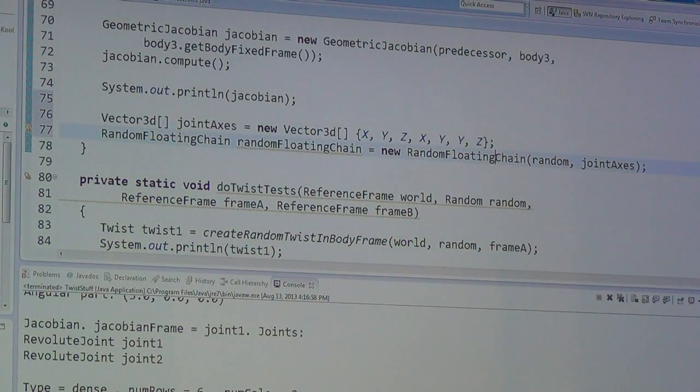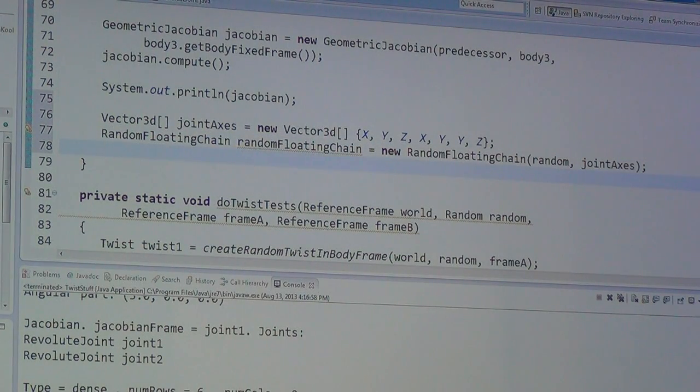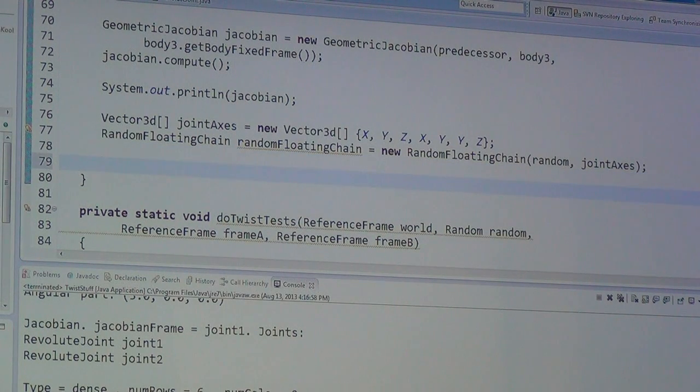So you just created a random robot, an arbitrary robot, that starts with a 6-degree-of-freedom joint, and then a whole bunch of revolute joints with all kinds of translations and rotations between them. But not fixed translations? Not fixed link lengths? They're random link lengths, but once they're chosen, they're fixed. There's no linear joints, they're all rotations, so it's all revolute joints. That's a good part for a genetic algorithm.